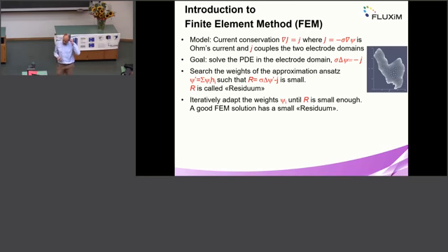And the FEM method basically is a numerical approximation which takes some shape functions and some coefficients. So we want to make an approximation, the superposition, where we need to optimize the psi_i, these coefficients need to be optimized such that the residuum, namely taking this equation, putting everything on one side, we would expect 0, but the R is never 0. It's always a numerical approximation. We want to minimize this R such that this equation is satisfied, right?